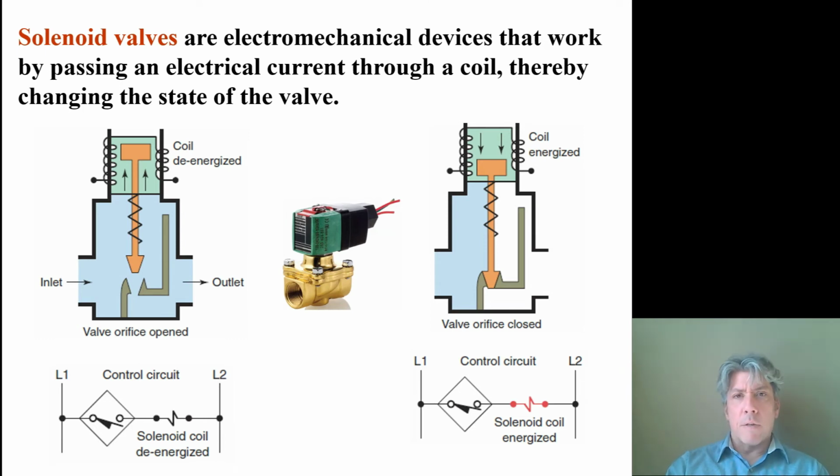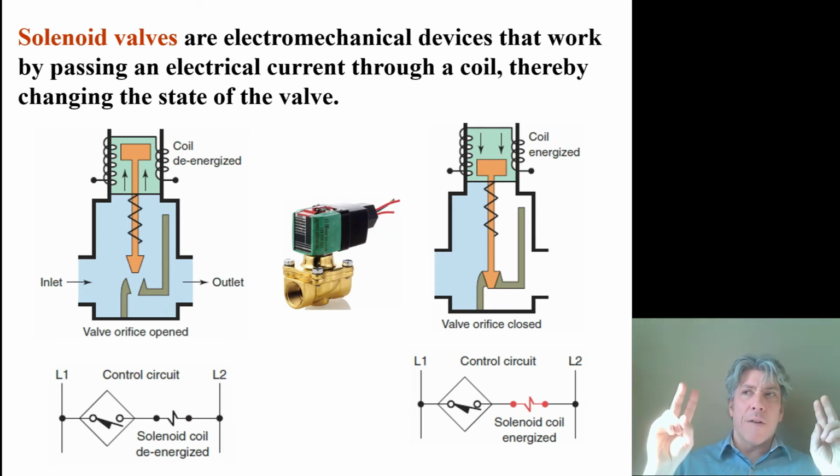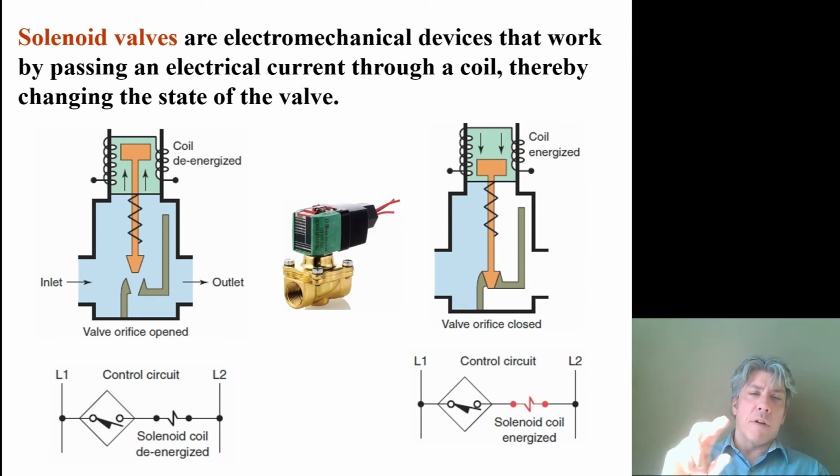In my home heating system, I bought some valves that are not really solenoid valves, but they are electromechanical valves. The way they work is they've got a little motor, and that motor has a gearbox on it, and when you apply power, the motor actually turns the gears, and I don't know if it closes or opens the valve. It doesn't really matter. It changes the state to the one. But when you remove power, it's kind of interesting because all the time that power is applied, the valve charges some supercapacitors, so that when you remove power, it's able to change state, and it has enough power stored up to change the valve's position.